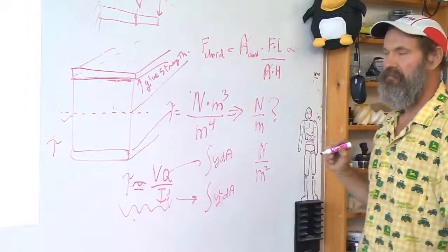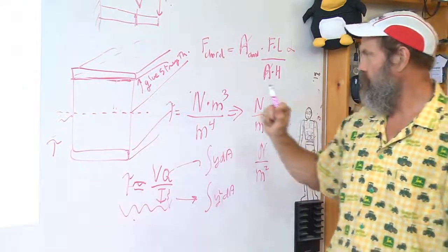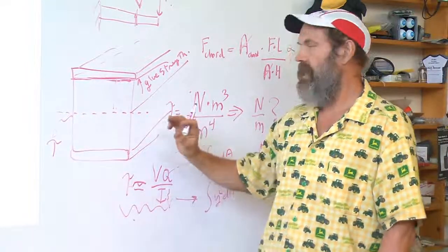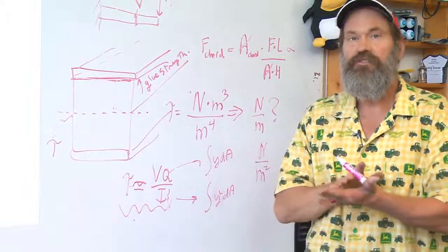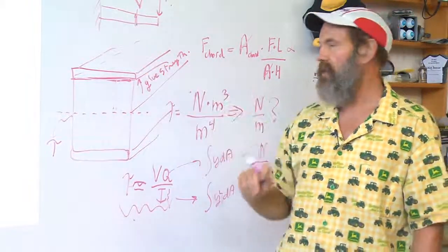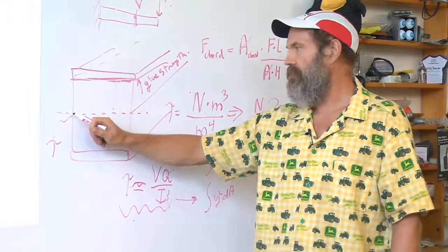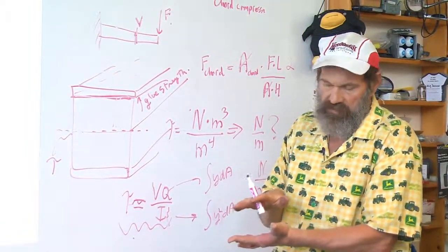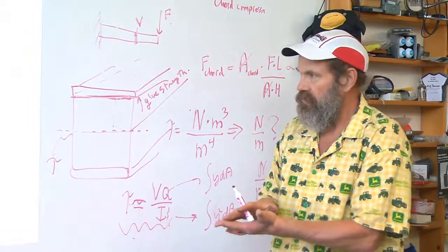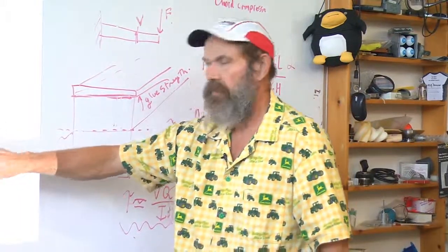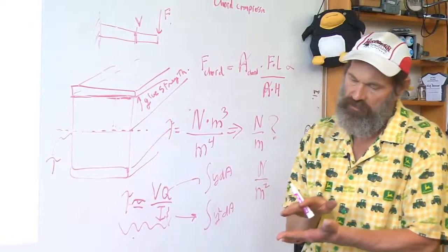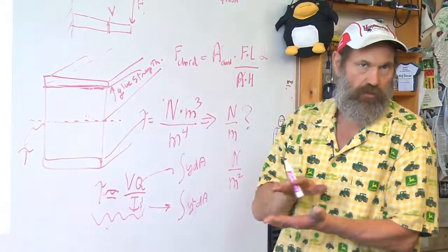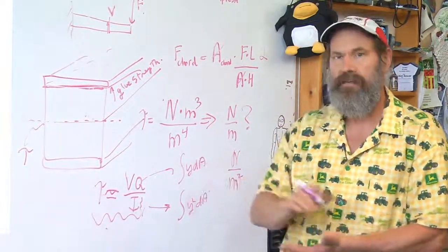Okay, go look it up. You use the ability to calculate the shear stress in a laminate to make sure that if you have a soft core like foam, the soft core, which is nice and lightweight, itself doesn't just shear through the middle. And you also have to check the shear stress in the glue layers to make sure the glue won't let go.